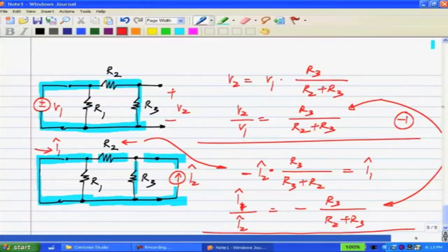And by using reciprocity theorem, you can get all of the original responses that you wanted. It turns out this is very useful, and it is used in circuit simulators also, particularly for noise analysis, where you have noises from many parts of the circuit affecting your output.